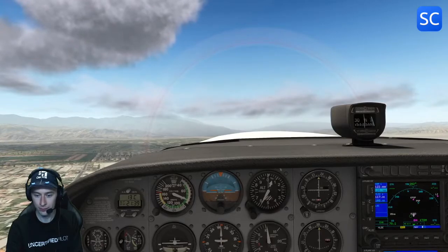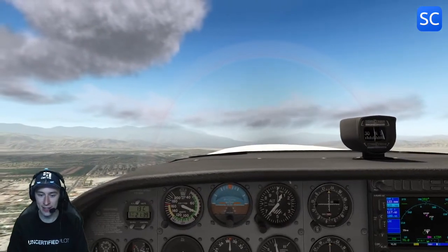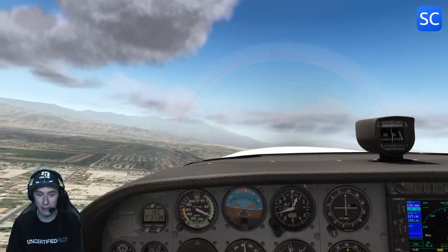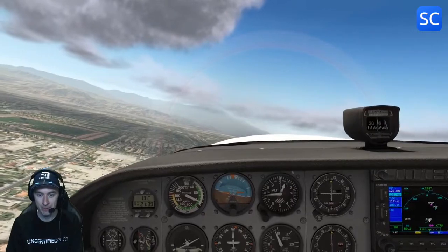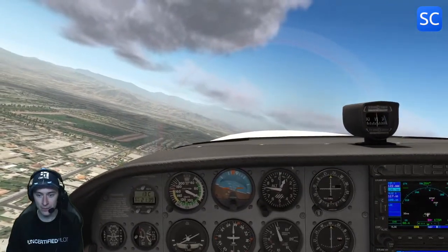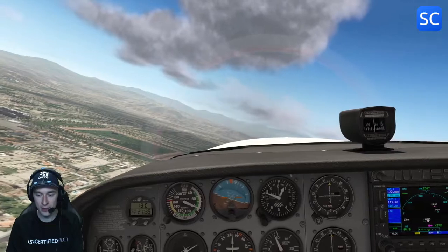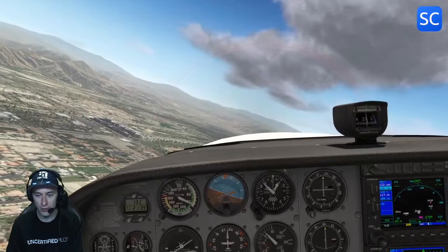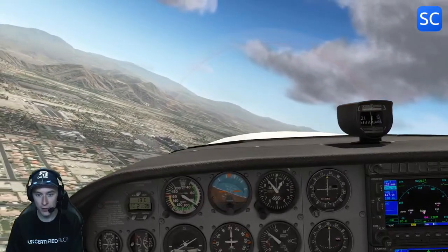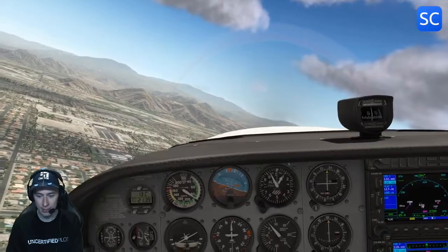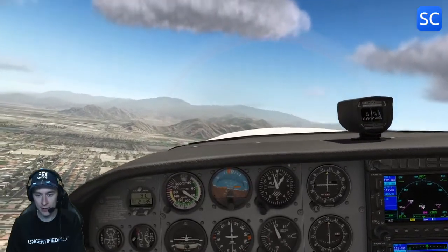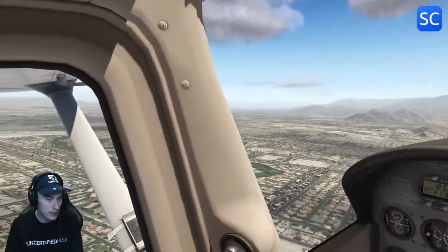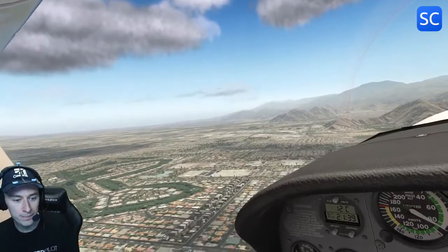There we go. And again, I think it's really highly recommended to get all of the add-ons to bring that flight realism into your sim. Left turn, a little bit of pedals. Bermuda Dunes traffic, Skyhawk Papa Hotel Tango Mike is turning left crosswind 28 for a downwind departure. Bermuda Dunes. A bit more nose up here. Heading bug is already to the right and already at 1,000 feet, but we can continue our climb because we're leaving this traffic pattern. Sure, no one is on that side. Good. Left pedals again.